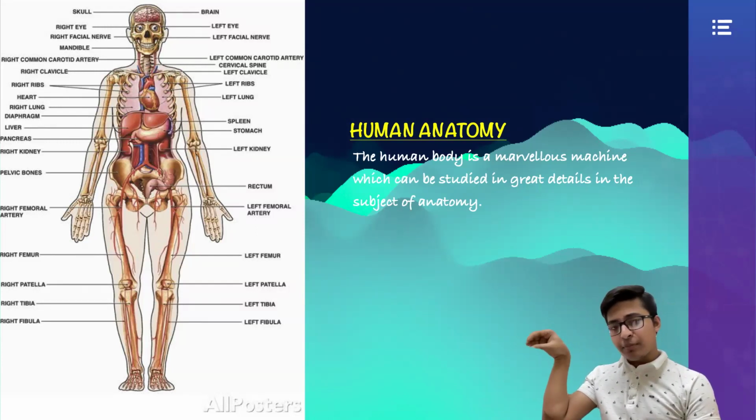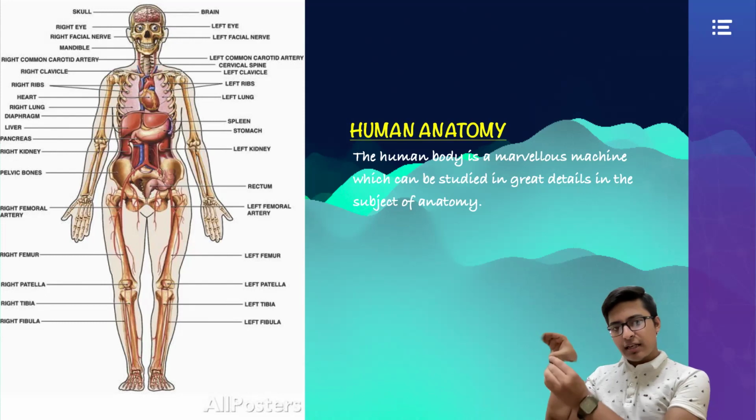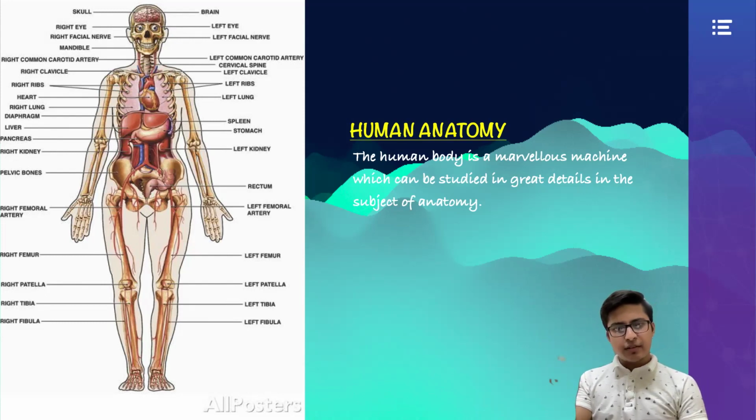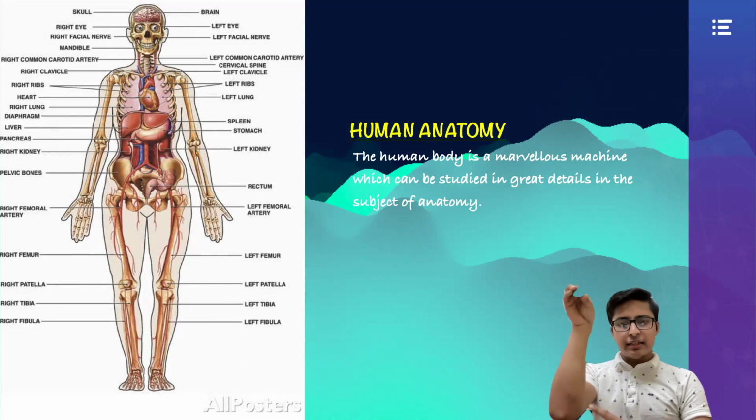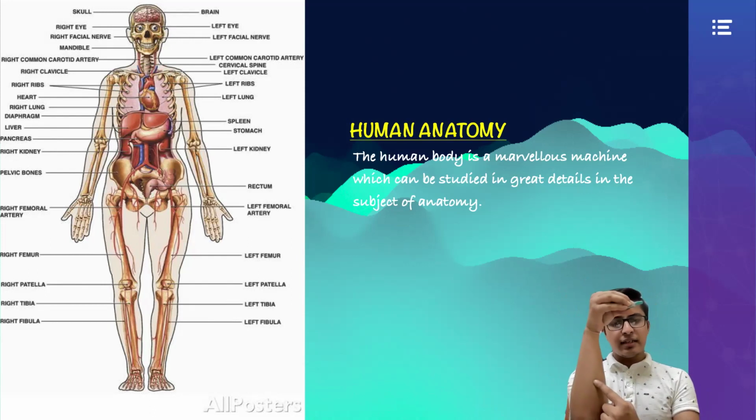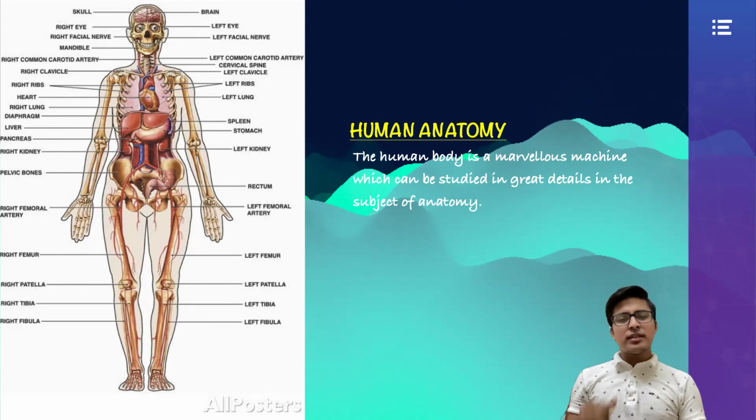It is the gripper over here, which grips the substance. It can grip some substance, right? There is a joint over here. The joint can move. It might rotate, it might elongate, right? There is a joint over here. So these are the joints basically. And this part is the link, right? This part is link. Okay. This is called the end effector. So you see, the simple robot, the simple thing, is also inspired from human arms.